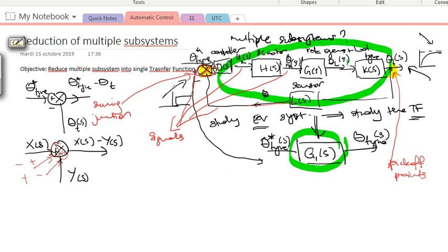But no, in automatic control, in this kind of block diagram, when we have a pickup point, the signal goes to both sides and it maintains its value of theta(t). So that's what pickup points are. And the components of block diagram, I recall it back to you: there are signals, there are summing junctions, and finally pickup points.